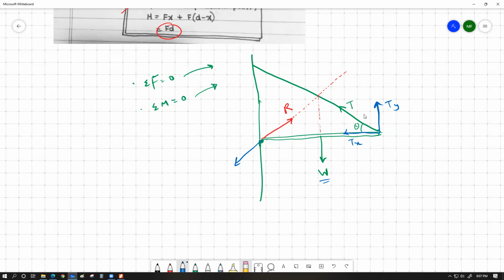That's really important. So the reaction force that I'm drawing from this point, working from the hinge, should be responsible for compensating for the resultant. So it must have a component of its own so that it can balance this leftward force. That essentially implies that the reaction force should have a component towards the right so that these two components can balance each other out.